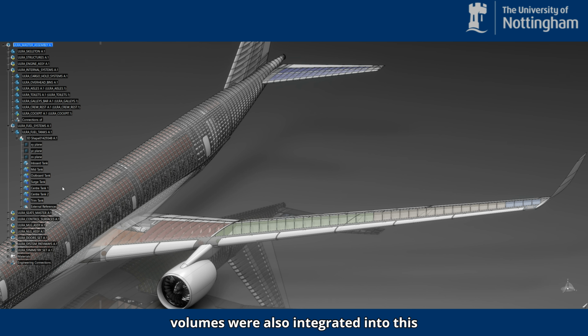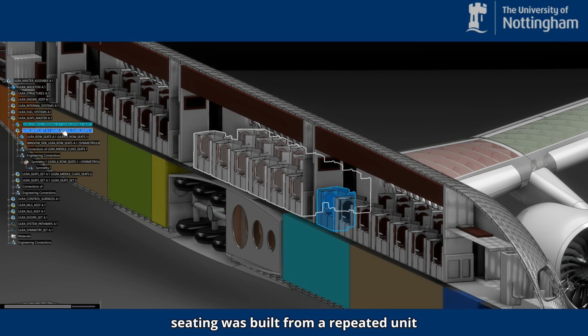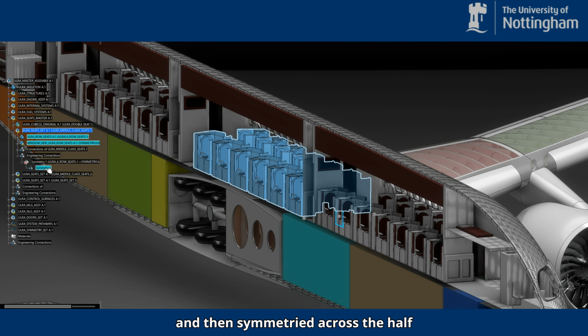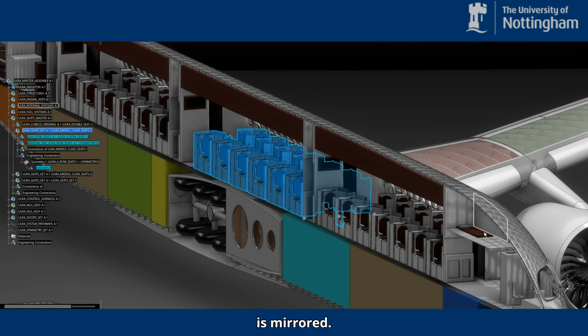The fuel volumes were also integrated into this layout, with the wing divided into the center, inboard, mid, and outboard regions, together with a surge tank near the tip, while the trim tank was located in the tail. Above the floor, the cabin was arranged as a 150-seat all-business class layout. From a modeling point of view, the seating was built from a repeated unit and then symmetried across the half model, so that the full arrangement is generated consistently once the aircraft is mirrored.